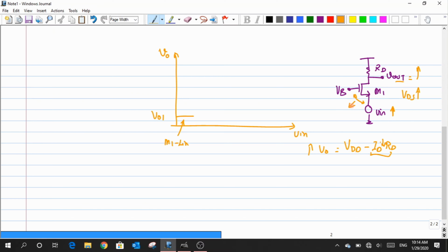Saturation, right? There is a particular point at which the VGS value is stepping down and my VDS value is stepping up. Previously I was in linear, and as this happens, both these values meet each other, and we call that the edge of saturation. Beyond which, if I further reduce the value of VGS, my VDS value would keep rising.